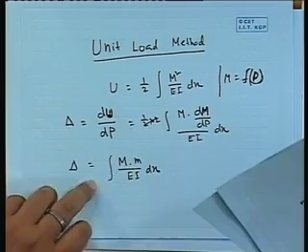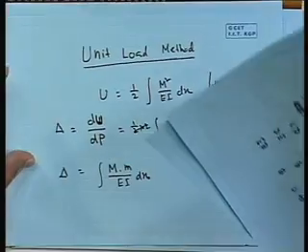What we have derived for the unit load is the integral of M small m by EI dx for different segments.